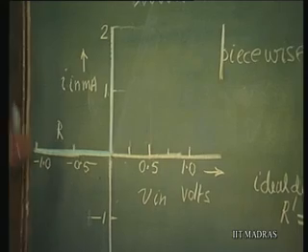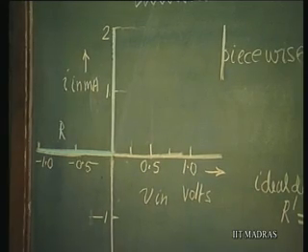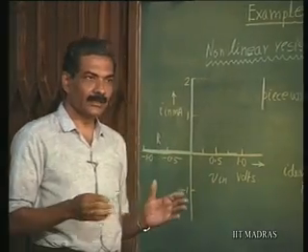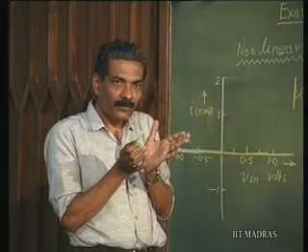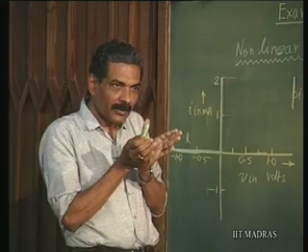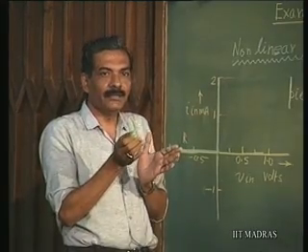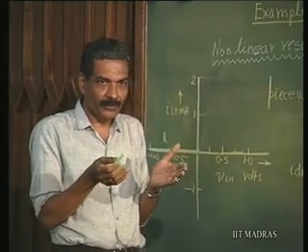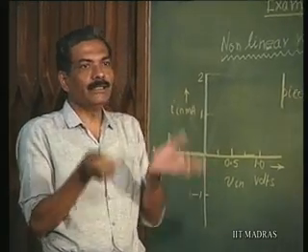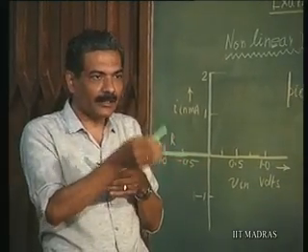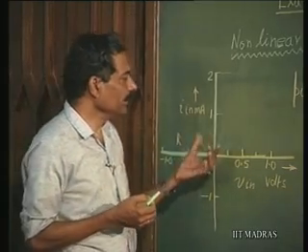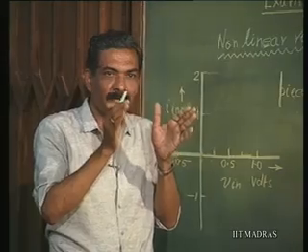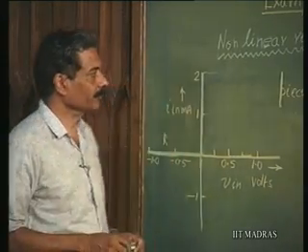In the other range, it is still linear and it takes on a different value. So, once again let us discuss resistance as the change in voltage divided by the change in current. When I apply a change in voltage, what is the change in current? The ratio of the change in voltage to the change in current gives me the resistance of these different regions, which are said to be piecewise linear.